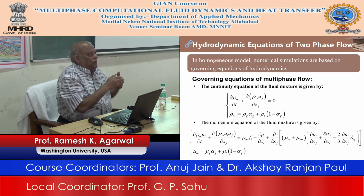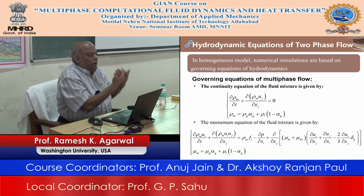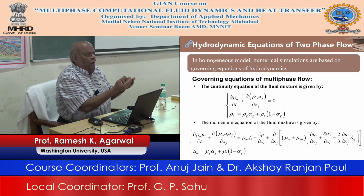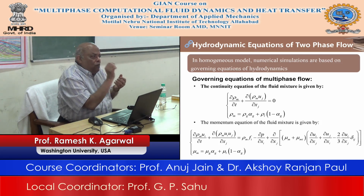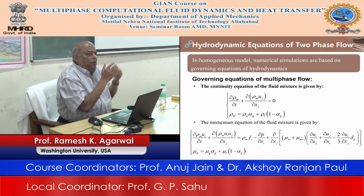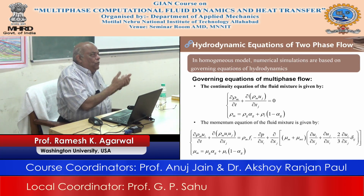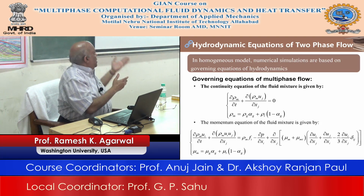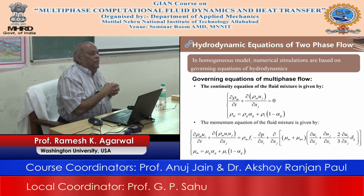In the calculation process, at time t equal to 0, you calculate the flow field, and that flow field gives you pressure and velocity, and then you know in which mesh cell the pressure has almost reached the vapor pressure, and so air has been created. There is an air pocket. We don't know where. So what you are doing there is using an initial value. Initially, tell me what is the value of alpha L and alpha G in this case.